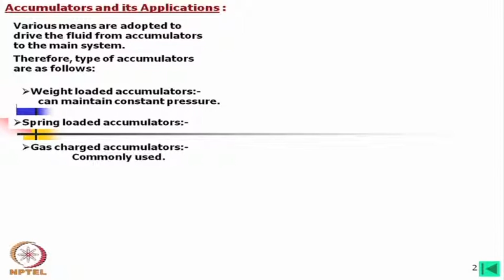In fact, weight loaded accumulators may be the best in that respect, but for high pressure you have to use a huge amount of load, and the construction of such an accumulator is difficult. And it is found that spring loaded can be used, but gas loaded is best, because in some cases you can regulate the gas pressure from the outside, although it is not normally done.